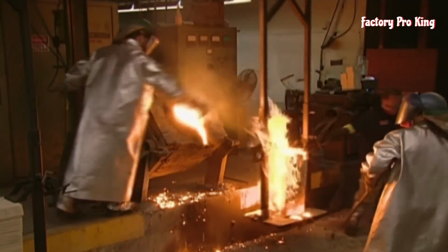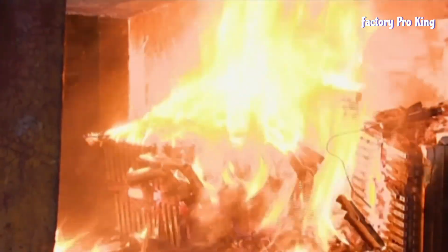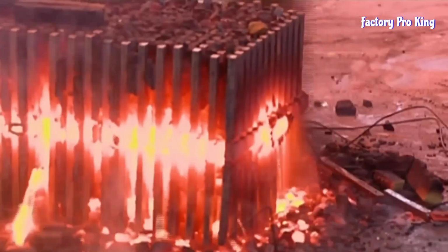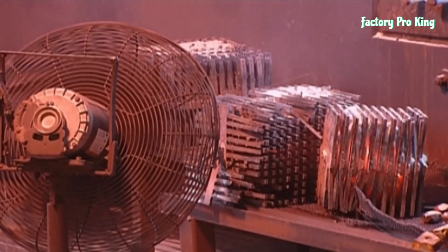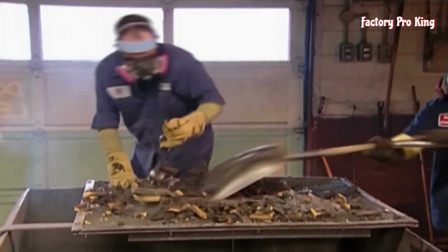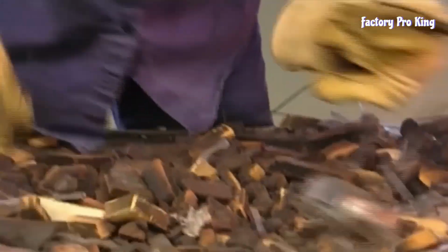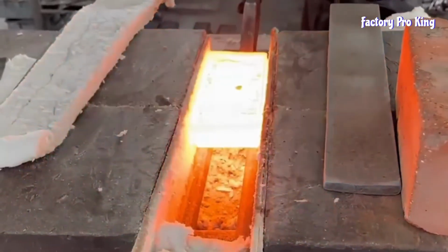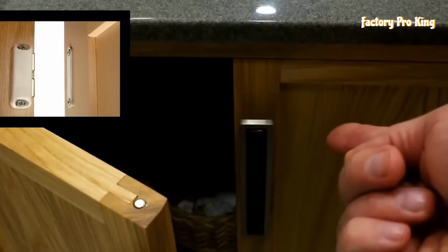The molds are cooled down, often by breaking them open with a sledgehammer, allowing air to penetrate and reduce the temperature. This step is essential for establishing the alloy's microstructure, influencing its magnetic characteristics. The cooled pieces are separated using a magnet. Initially, these mold pieces act like ordinary metal because they haven't been magnetized yet. They undergo heat treatment in an electrical furnace and are then mildly magnetized using an electromagnetic coil.